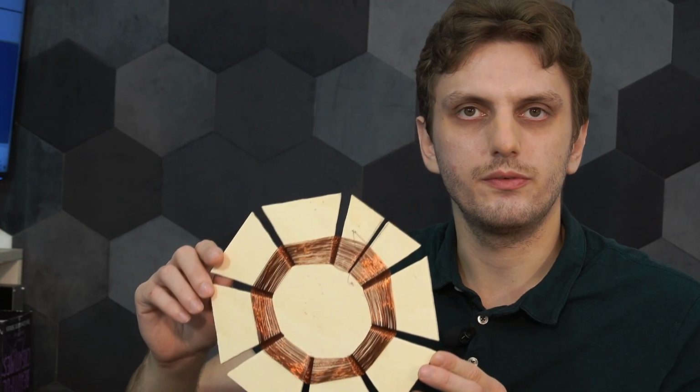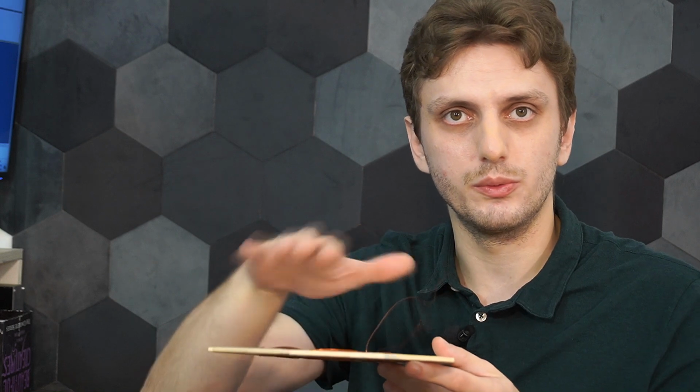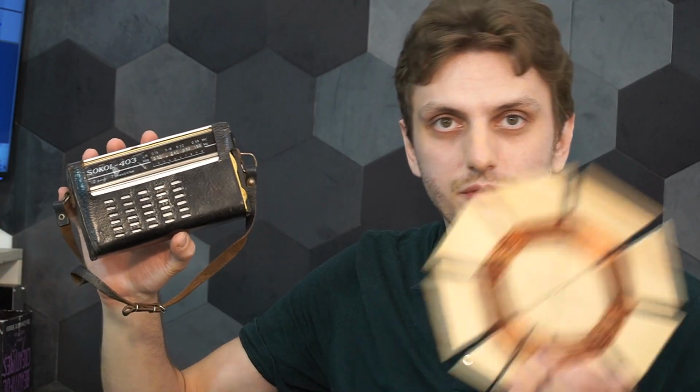And you have this sort of inductor commonly used with things like wireless charging or induction heating. And that is because you don't want to have a single position in space where you can charge your phone. You want it to work wherever you put the phone onto the coil. So for this application, since we don't want to have a very precise alignment between our receiver and the coil, we can go with this sort of inductor shape.